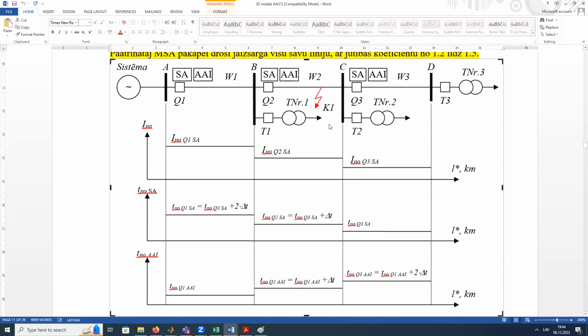Ordinary scenario, but we know this protection knows that there is a fault, and we are going to run a recloser with a knowledge of a fault, with hope that it is temporary, but with a knowledge that there is a fault. And in this case, if we know that there is a fault and this relay protection should disconnect this line, yes, we disable time delay for the recloser operation time.